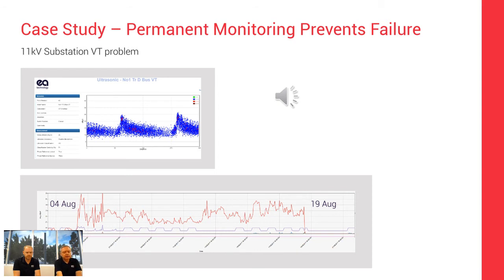We actually went into the substation just before that happened, and we were able to take a handheld survey or handheld measurement. You can see on the Ultra Plus there it is showing 2 phase-locked clusters of activity 180 degrees apart, which indicates PD, and the sound clip, which isn't playing, was again indicative of PD, and the algorithm was classifying that as partial discharge activity.